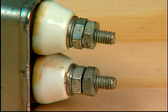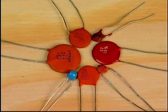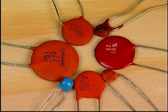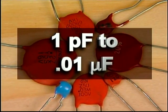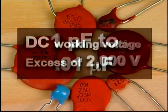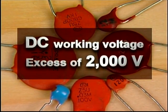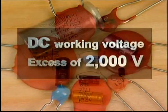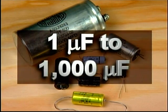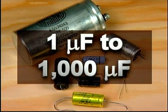Other types are also used. Ceramic capacitors use ceramic as the dielectric and a film of silver for the plates. They range in value from 1 picofarad to 0.01 microfarad and have a DC working voltage in excess of 2000 volts. Electrolytic capacitors are used for capacitance values from 1 to 1000 microfarads.